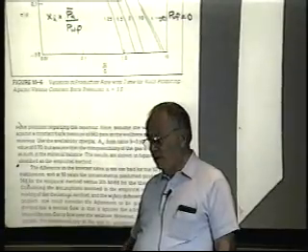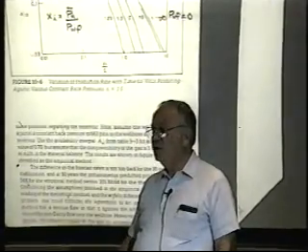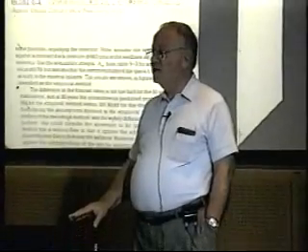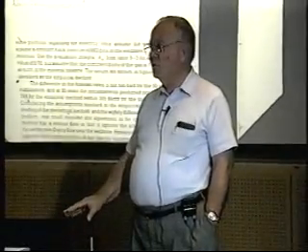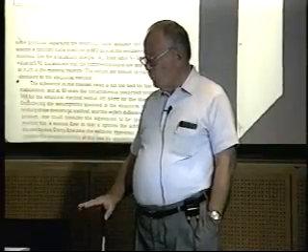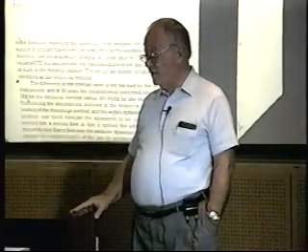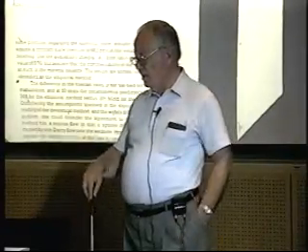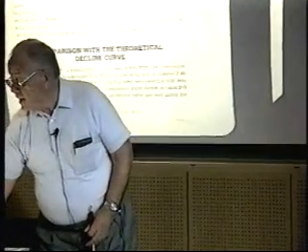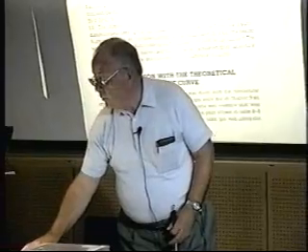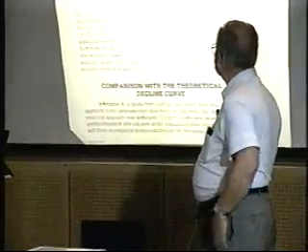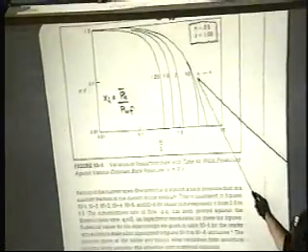So the tables are in here. If you want to utilize specific back pressure in an early period where you haven't dropped the line pressure yet to some lower values, you can take this information or these tables and plot up your own log-log type curve. That's for an N of 0.5. One reason I like to include that, an N of 0.5, this is exponential.